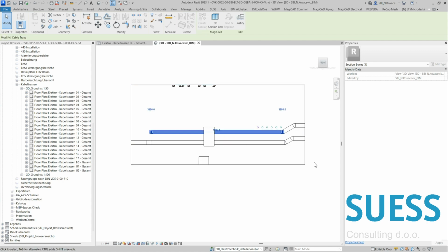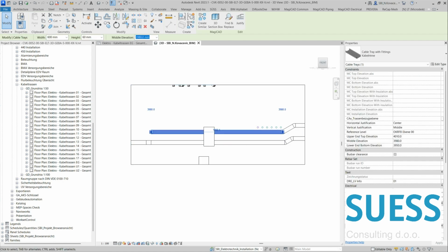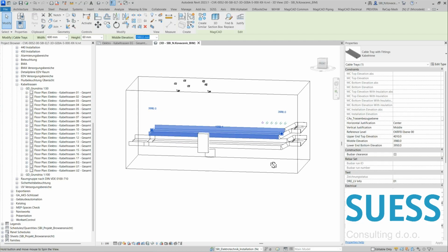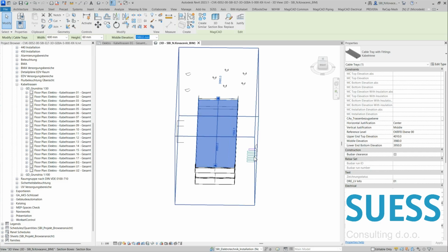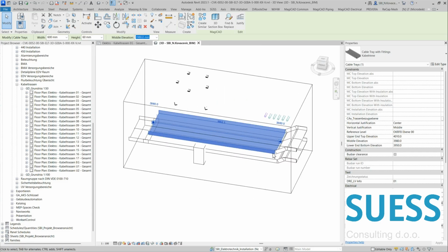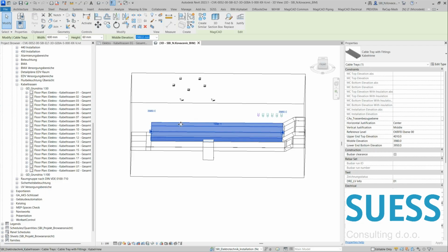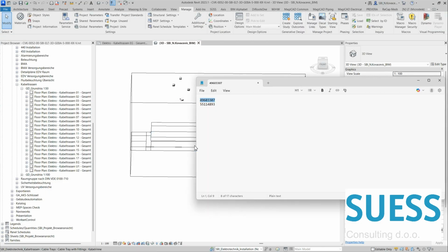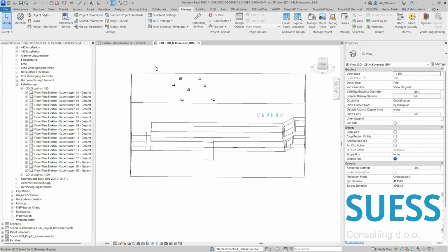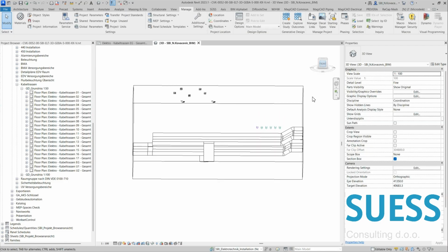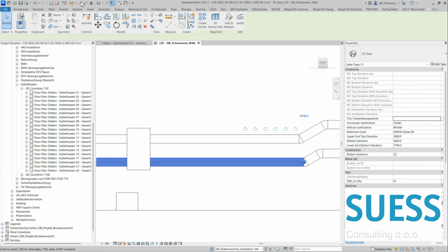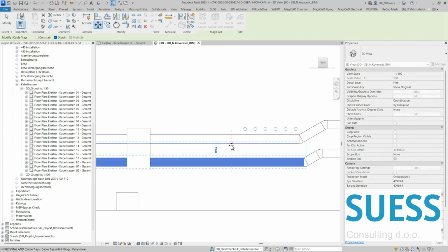So maybe let's see what the length is over here. It's 2 meters. I think this is manageable. But this will be a problem to secure the hanger position. Oh no, because those pipes will end over here, so we can place a hanger over here and over here, and this should be fine. Now let's check that other ID. No, before that, let's just measure the vertical distance. Is it really less than 100? It is exactly 100, so it is less than or equal to 100.